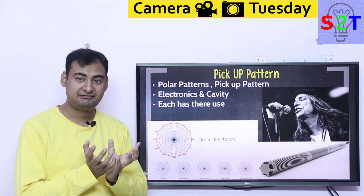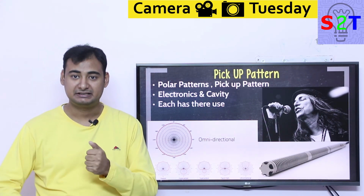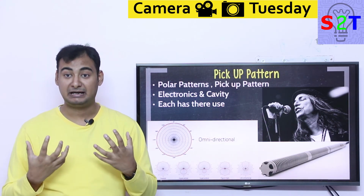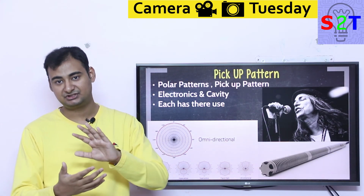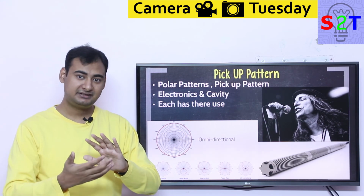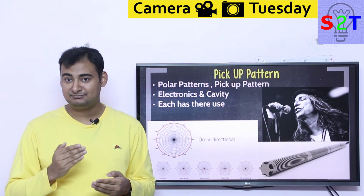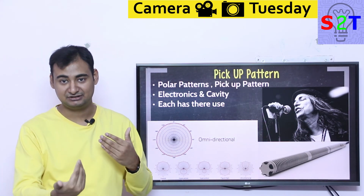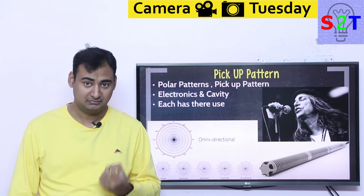Then they design the cavity around it in such a way that a cavity that is near to you receives your sound, and a cavity around from you is receiving the ambient background noise. Because background noise is coming from both sides, the front chamber is also receiving the background noise and the rear chamber is also vibrating, they cancel each other out, and only your voice is unbalanced, because on the back end you are not screaming for the back side, that is received. That's how they make an analog noise cancellation microphone.